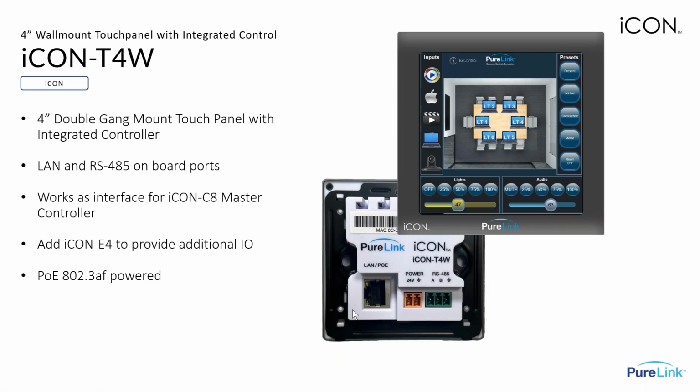Okay, so first up, as we look at each piece of hardware, we're going to look at the T4W. Now the T4W is a 4-inch touch panel, completely programmable. We're showing a sample program on the screen here, but of course you can design anything any way you want on that, what we call canvas, to make sense for your application. And this fits in a standard US 2-gang enclosure, and it's powered from PoE 802.3 AF, and in fact it only uses about half of that power. So it's a very low power device.